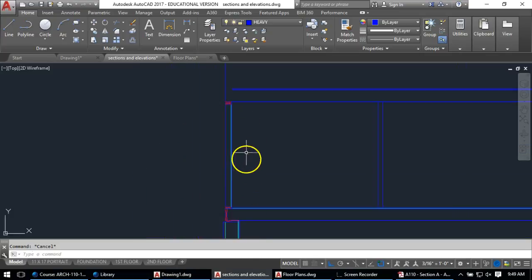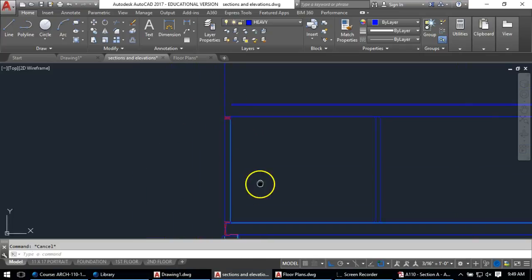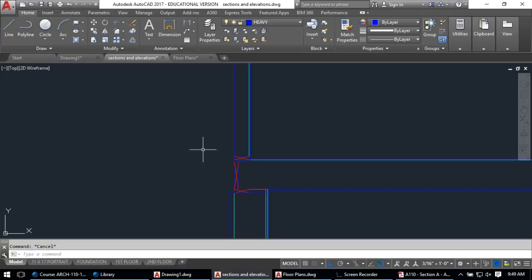Okay, and then I guess we have some exterior finish. Let's see what the notes say on this. I'm just reading the numbers on each drawing, both the big and the small. There's a 1/2 inch of plywood sheathing, and then there are wood shingles over 30-pound building paper.